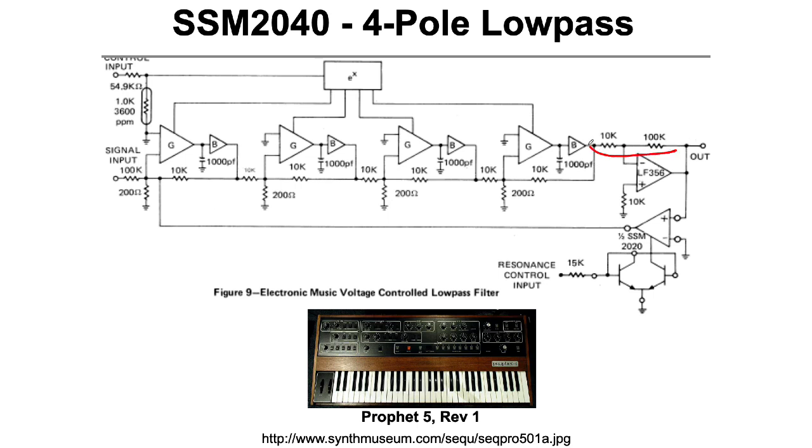There's a gain of 10 at the output here that you get through this op-amp, since I have a feedback resistance of 100K and an input resistance for this inverting setup of 10K. So from that gain of 10, you might expect there's an attenuation by a factor of 10 elsewhere, and you actually get that here. There's no harm in analyzing the circuit by imagining that you don't have one of these zeros here, so that 10K matches all the rest of the 10Ks we see everywhere else. And then you could think of that additional factor of 10 as just affecting the signal right at the input.